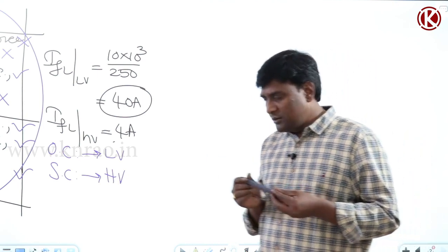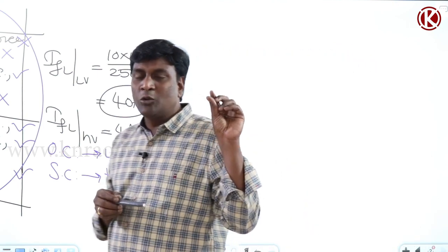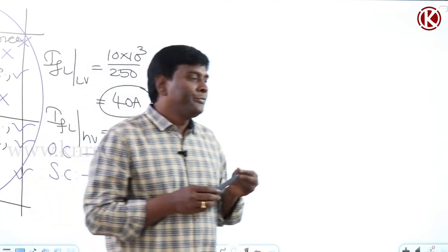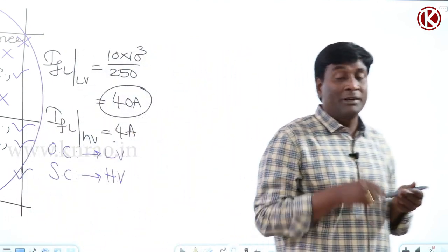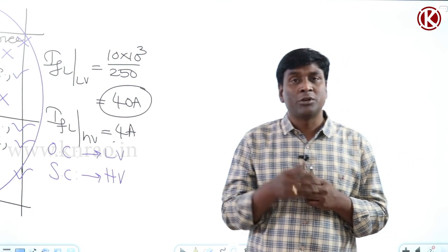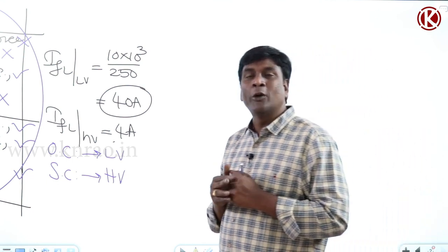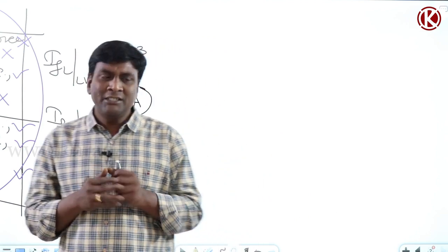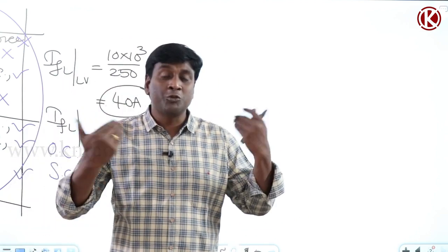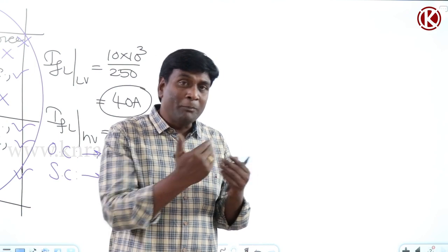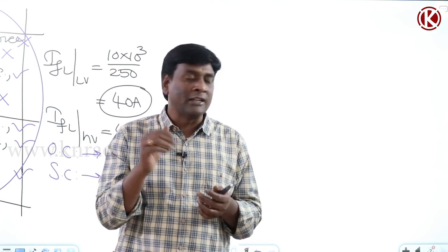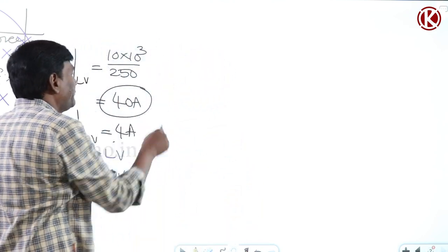As I told you previously also, air gap in the rotating machine should be less or should be more? Should be less. Yes, it should be less, in order to reduce the magnetizing component of current or field current. It should be more to reduce noise levels. So in machines, both the contradictory statements we should be able to digest, and depending upon the application, we have to select which type of analysis should be done. For example,